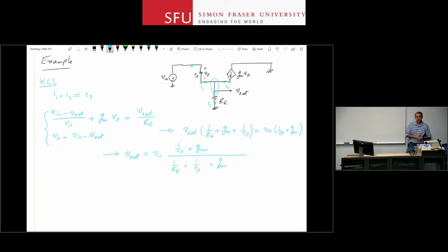You just use V in to represent it, hopefully with some known, at least statistical, properties for that V in. And then you calculate the ratios of different voltages in your circuit to that input voltage, or currents to that input voltage, or input signal in general, and then go and solve the circuit.